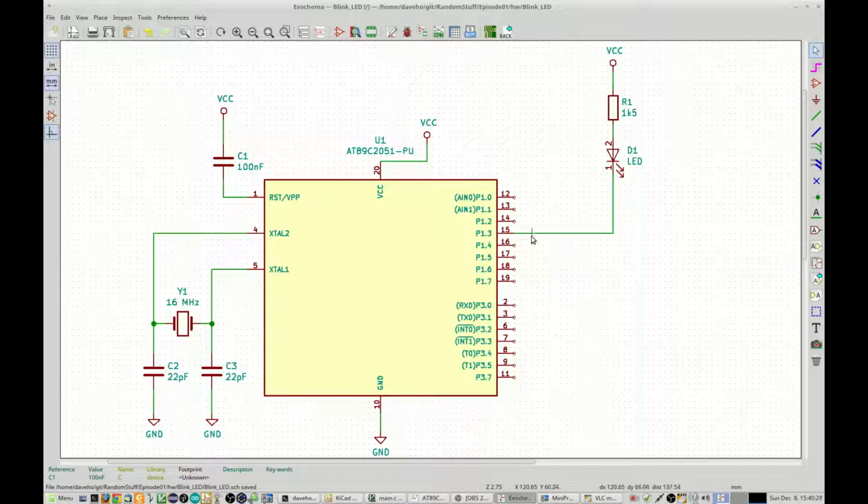So interestingly, on the 8051, the output pins can sink current to ground, but they cannot source current. So we could not have hooked up this LED to have a high voltage at its anode. Basically, only a tiny amount of current can actually be supplied on the output pin when the logic level is high, but when the output level is low, we can sink a reasonably large amount of current, certainly enough to light up this LED.